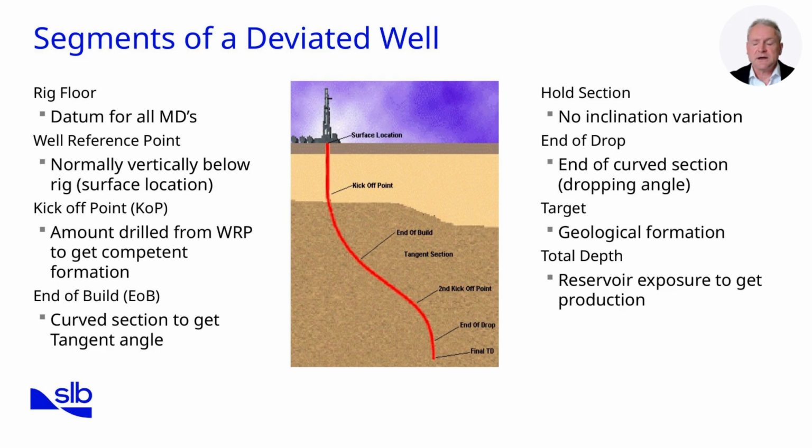To avoid hole cleaning issues, angles should be either below approximately 40 degrees or above approximately 60 degrees. Angles between 40 to 60 degrees are problematic, often requiring corrective design changes. End of drop, a section where inclination decreases. Drop sections are challenging due to weight transfer, shock, and vibration caused by side forces. A rule of thumb is to keep drop doglegs lower than build doglegs.